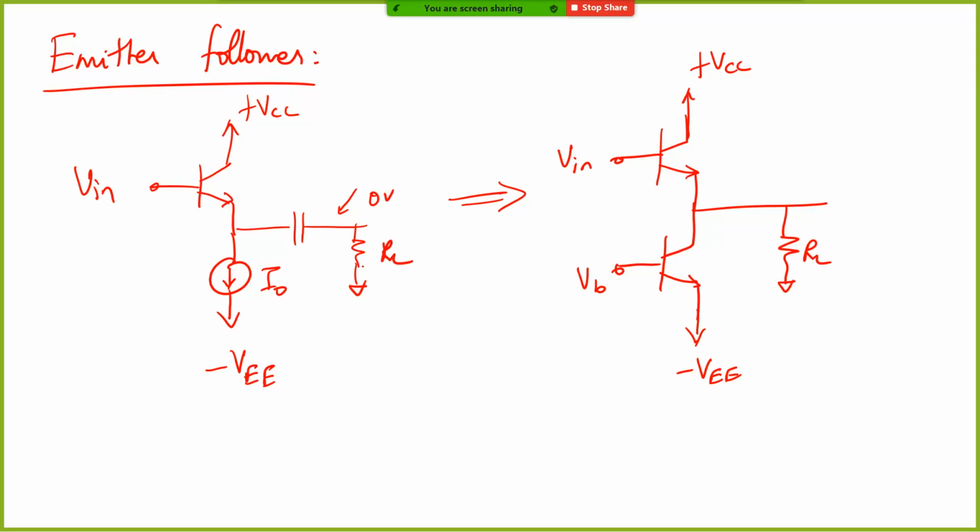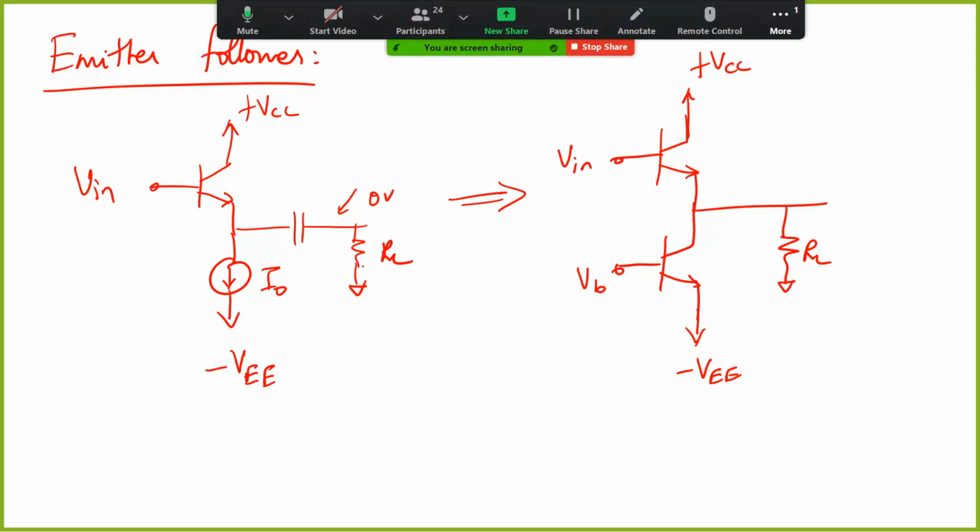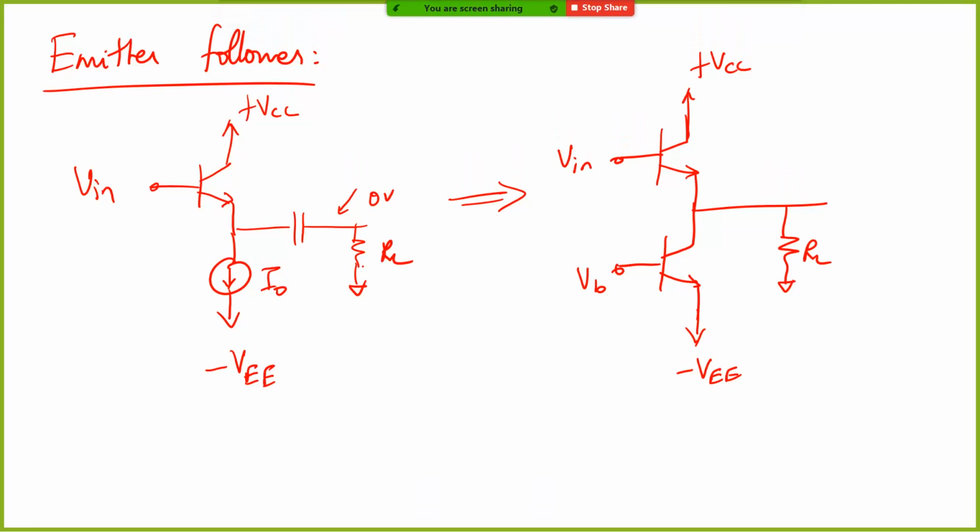Or you can also get rid of it. There are certain circuit architectures where you can do certain things to get rid of this capacitor, because you can bias it and do certain interesting things here, such that the DC voltage is always 0 there, so DC current does not flow through the load. You can maybe add some additional circuitry which can do that.